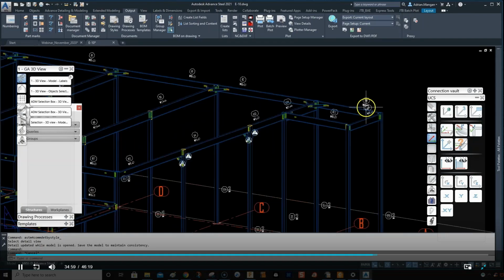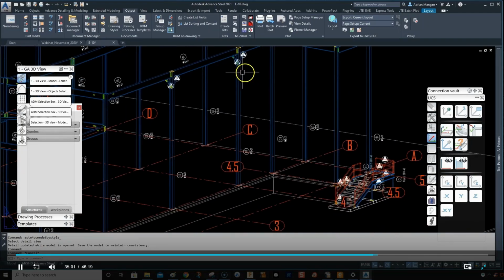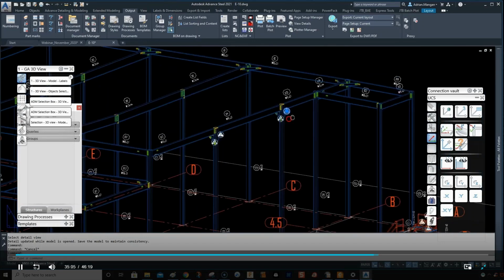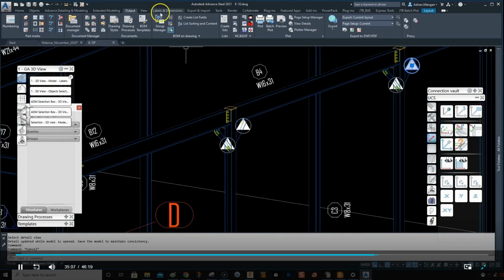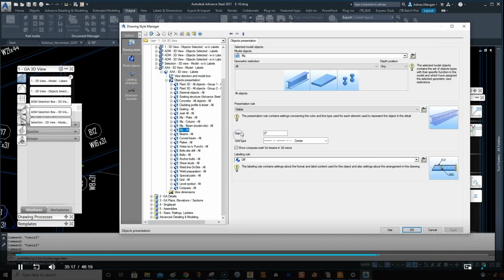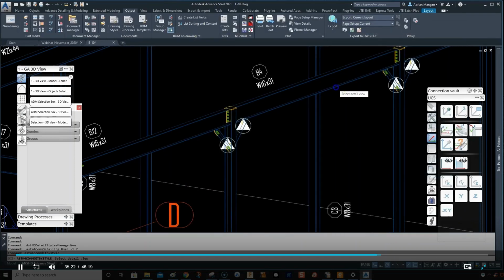Now I also need to remove the compass marks, because you can see the compass marks are here for these, even though I've turned the labeling off, because they're still visible. So let's go back in quickly, open it, go to our main parts, double click, turn the compasses off, apply, okay.